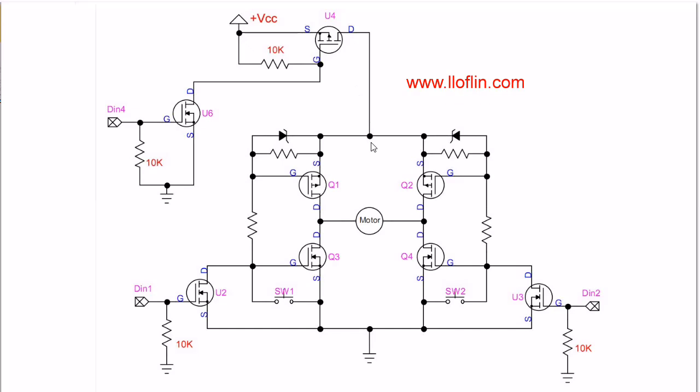I've never had a problem with shoot-through. Shoot-through is where, say, Q1 and Q3 are both partially on when we're switching them, and that creates a dead short to ground, possibly blowing the parts or blowing traces off the board or whatever.